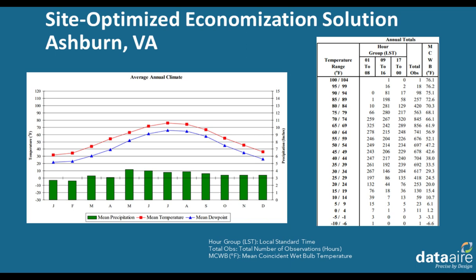But from that, we can now figure out how many hours this site is experiencing a certain temperature in that certain range, and we can do calculations on this with much more detail. So in addition, we also have the wet bulb temperature, which is also recorded for each of these bin ranges. So that's critical, again, because I mentioned if you're using an evaporative cooling solution for your cooling tower or fluid cooler, then you would need to know what that wet bulb temperature is.